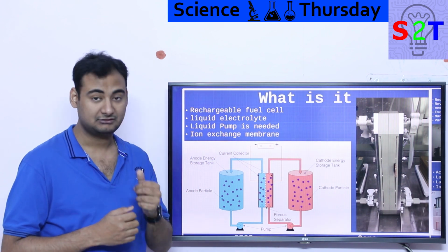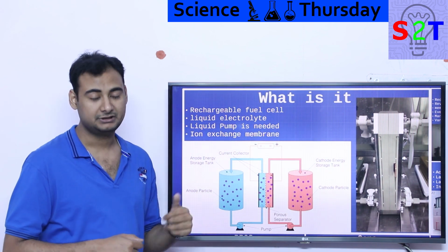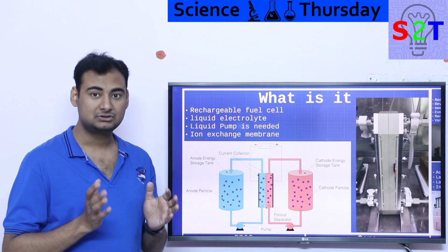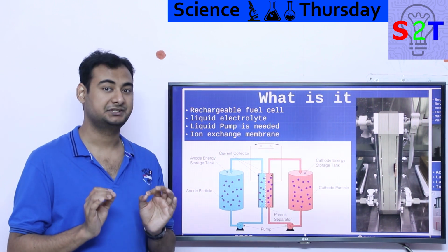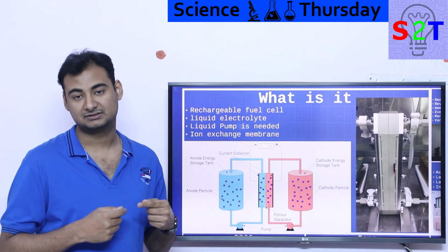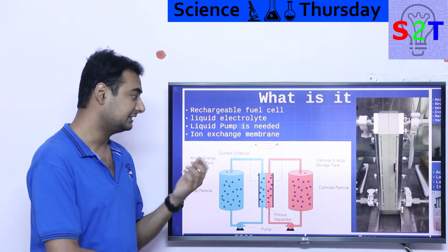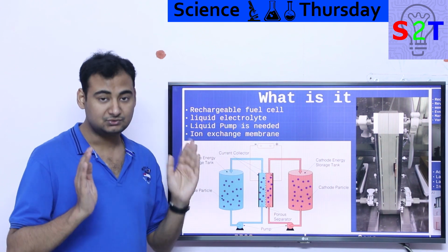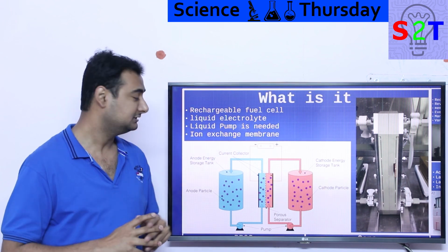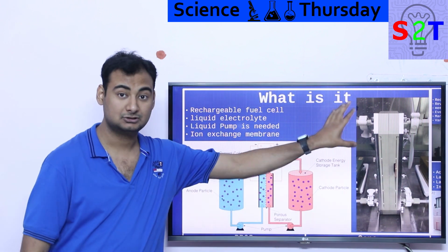And the electrolyte, basically, if you are familiar with any types of battery, you know they have two components. Basically, you have cathode and you have anode. In this sort of chemistry or architecture, flow cell battery, both of them are in liquid state. That is the most critical component. They are in liquid state and they generally require liquid pumps to circulate them. It's not like a heat pipe where the heat energy itself moves the fluid inside. It's not like electricity or the chemical energy is moving them. You have to have a pump that is circulating them, and all the reaction, all the magic, happens in ion exchange membranes. So that's the reality. That's the quote-unquote cell.